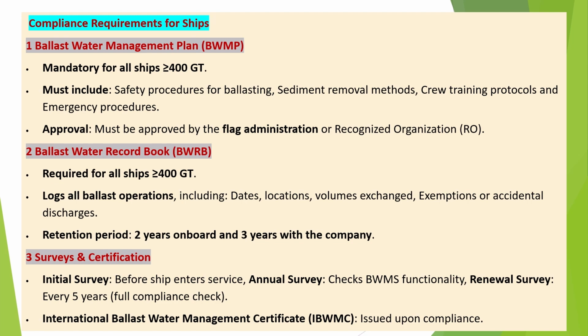2. Ballast Water Record Book, BWRB. Required for all ships greater than or equal to 400 GT. Logs all ballast operations, including dates, locations, volumes exchanged, exemptions or accidental discharges. Retention period, 2 years on board and 3 years with the company.